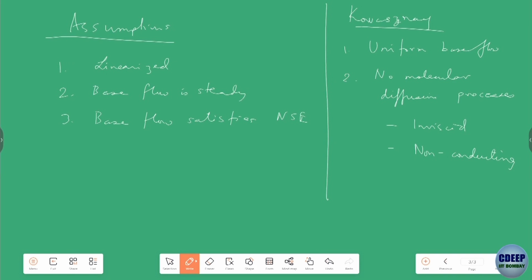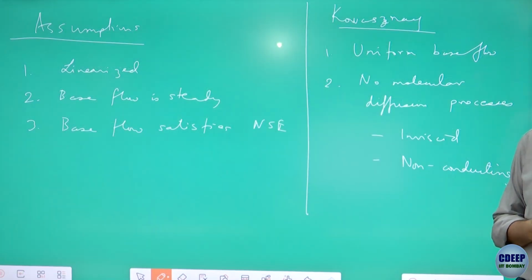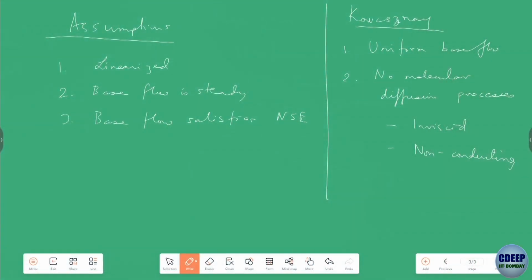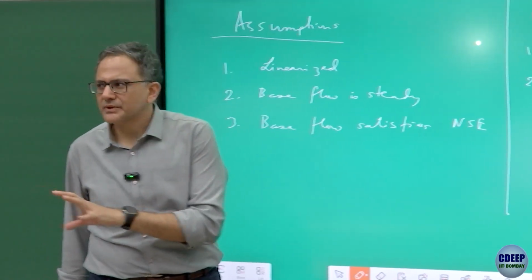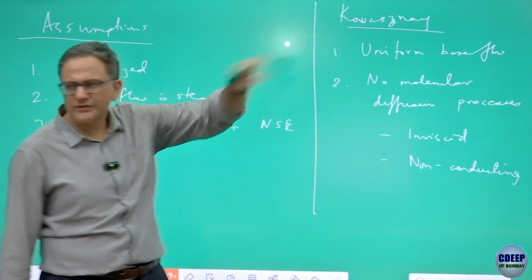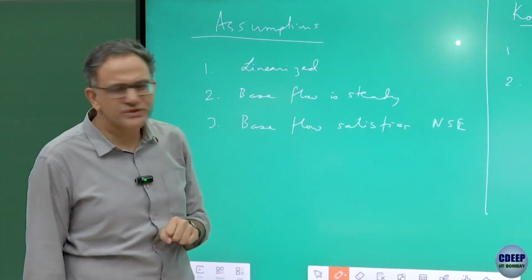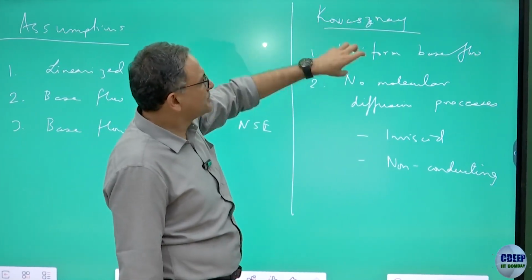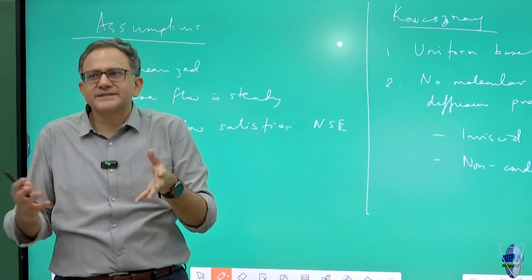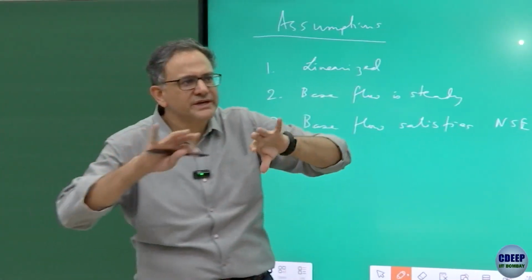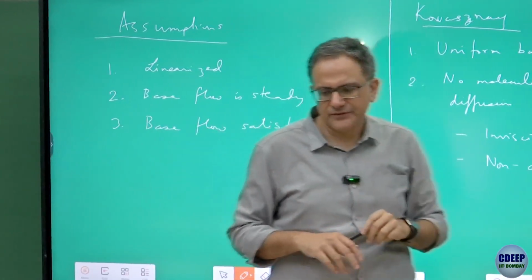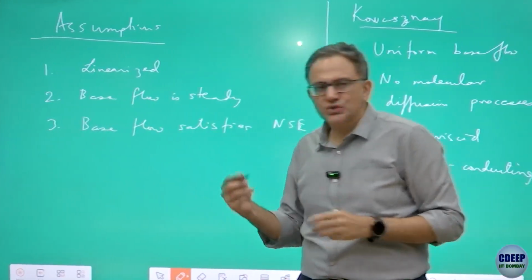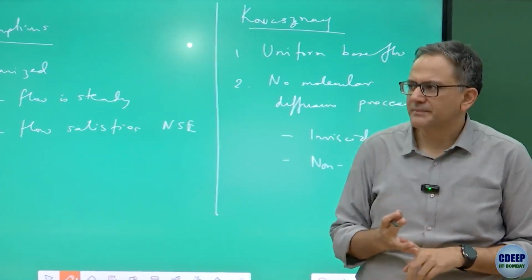Because this course is running in the aerospace engineering department, you are all okay with inviscid, because we have seen the power of inviscid for our aerodynamics, and so you are probably not questioning this part. The uniform base flow is definitely not the most general that you can have. So Kovásznay had to bring in the uniform base flow to decompose or decouple all those three components of linearized fluctuations, to show what is acoustic, which is the irrotational and isentropic part of the fluctuations.